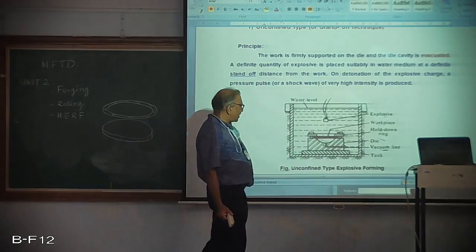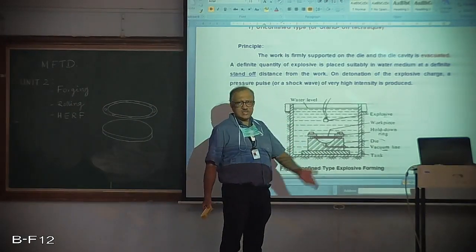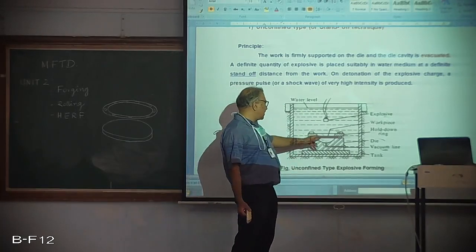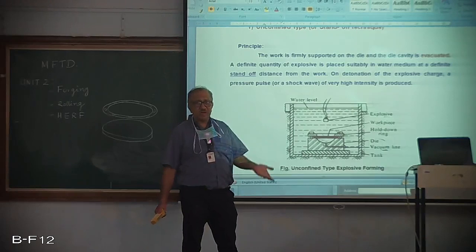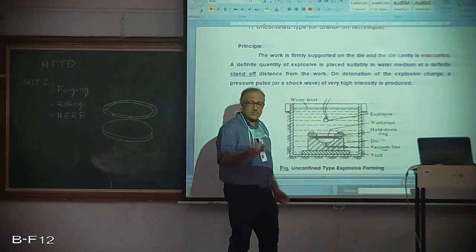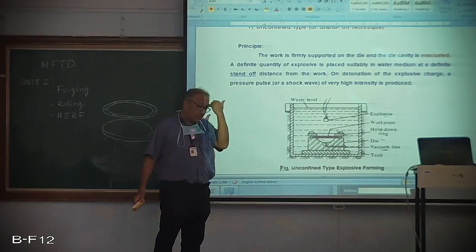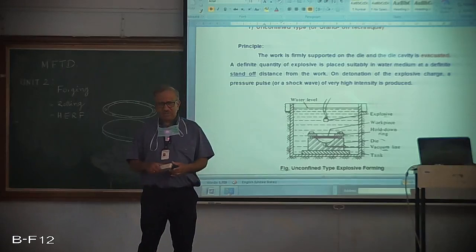So, to avoid adiabatic heating effects like overheating, damaging the metallurgical properties of the metal, and also to prevent any possible partial melting of the workpiece, we need vacuum. And that makes the process a little more complex, because maintaining vacuum is quite complicated.